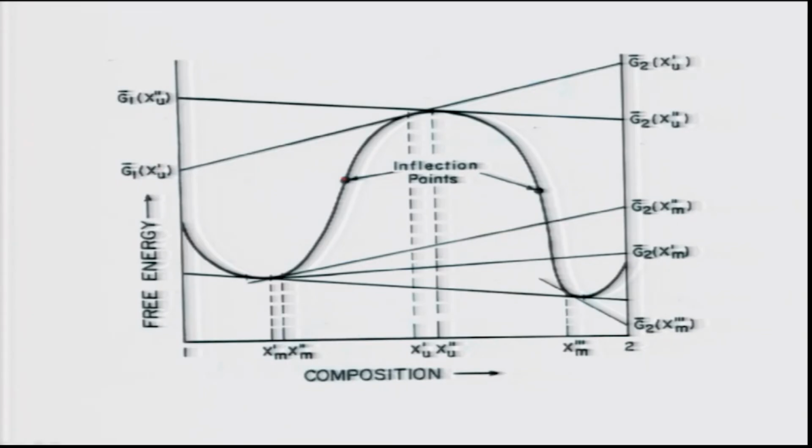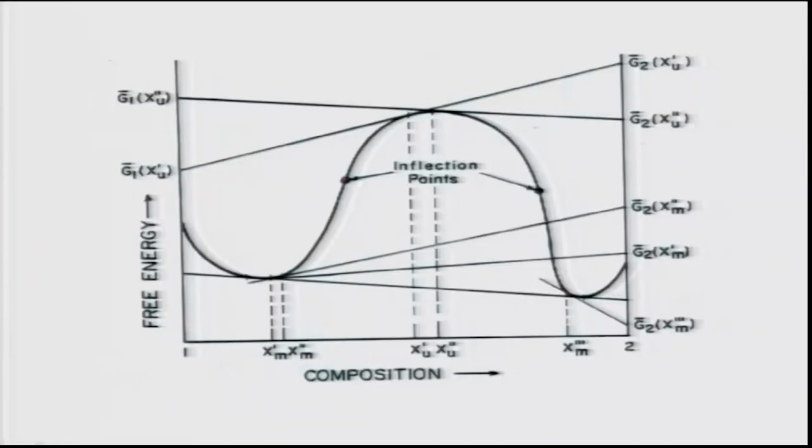Okay, this is taken directly from the book of Jena and Chaturvedi, so I have not changed the symbols. The symbols are not simple ones, by the way, but it explains the things very nicely. So this is the chemical potential of component 1, chemical potential of component 2, correct. Now the question is this: any kind of decomposition must lead to reduction of the chemical potential, that we know, because chemical potential must be equal, then only the transformation will be the same.